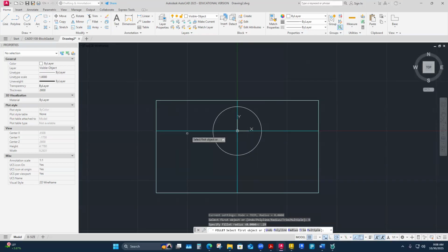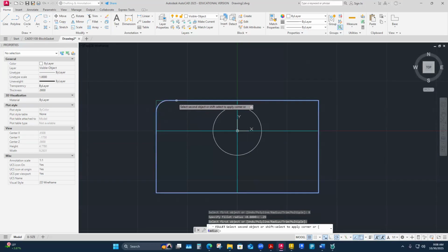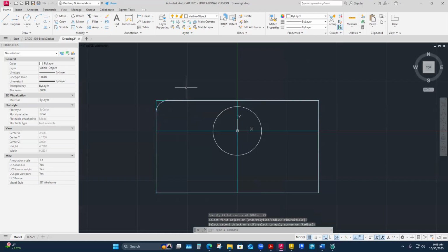Because I've done both, this isn't going to be such a problem. But if you're used to not doing construction work and then you do a fillet like this, you might need to pull dimensions. Most of these dimensions are based off the axis, so it's not a huge thing. But every once in a while, if you want to pull from an endpoint to locate stuff and you've done a fillet, it gets annoying to locate because you've lost the exact intersection point. So I like my construction line, so I can do that to the radius and still keep a construction point out there at that extent.